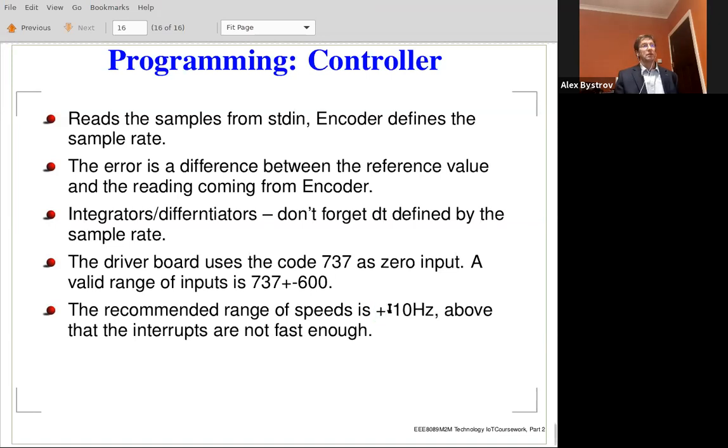And at the speed of 10 Hertz, with 500 pulses per rotation, that is basically the frequency where the lag in the interrupt system will start dominating the system. At a speed slightly higher than that, it will eventually fail, becoming first very inaccurate and then starting to fail. Our speed for our implementation is 2 Hertz, well within this range. So there should be no problem.